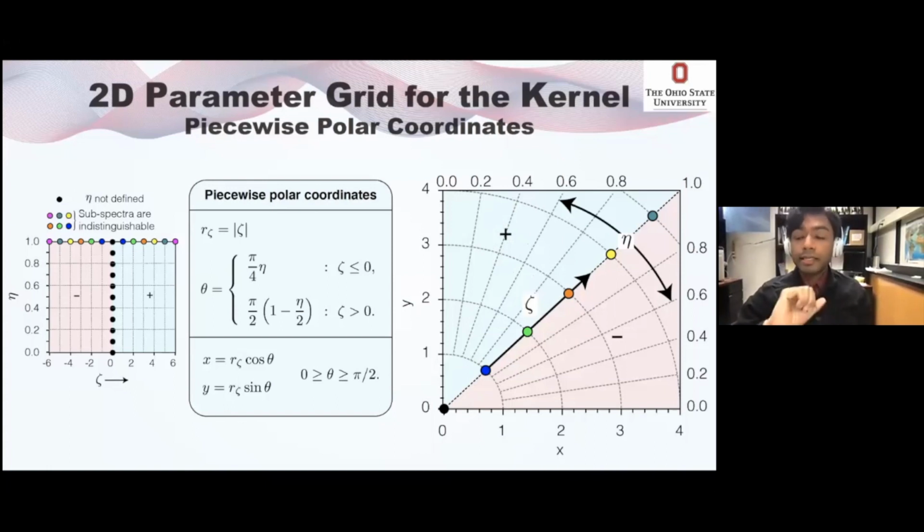And the asymmetry parameter is defined such that if you're along the x-axis, it's 0. And as you go up the angle to 45 degrees, eta uniformly increases from 0 all the way to 1. And similarly, for the positive anisotropy, if you're along the y-axis, eta is 0. And then if you go down from 90 degrees all the way to 45 degrees, eta uniformly increases from 0 to 1. And in the middle is just a mathematical representation of what I just illustrated in the figure.